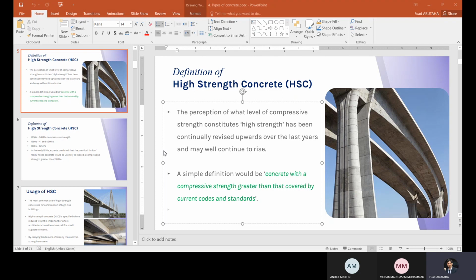not only because of segregation. It has so many other factors. One of them is segregation, that a high water content is one of the factors that lead to segregation. But even if we don't have segregation but still have a high water cement ratio, we still have lower strength. So the first and most sensitive factor that affects the strength of concrete is the water cement ratio. So you need to know how water cement ratio will affect the strength of the concrete.